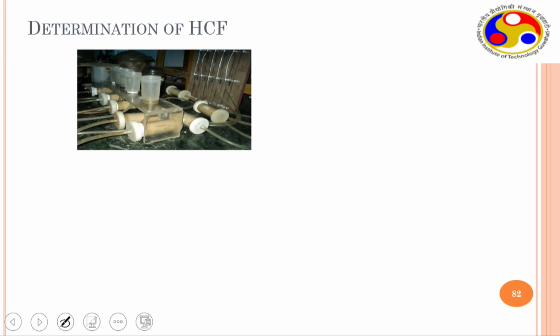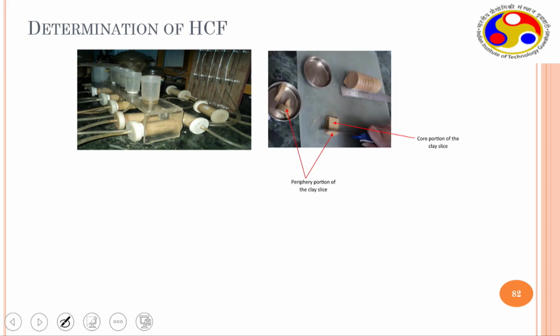I took a soil sample. This is our work. This is bentonite, right? Bentonite compacted at different densities, starting from 1.2 to even 1.8 gram per centimeter cube dry density, and connected to water reservoirs. So water is flowing, you could see water is here, water is here. So there's a wetting front which is moving in the soil samples.